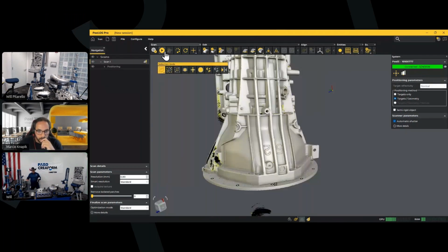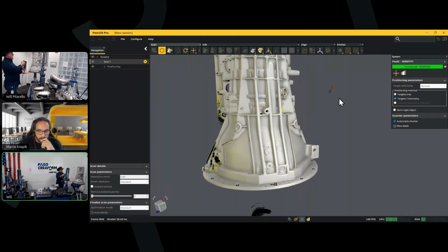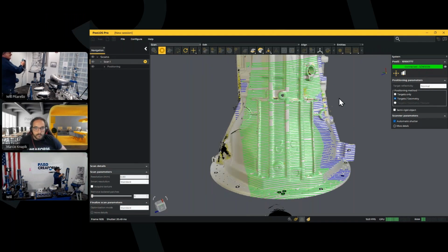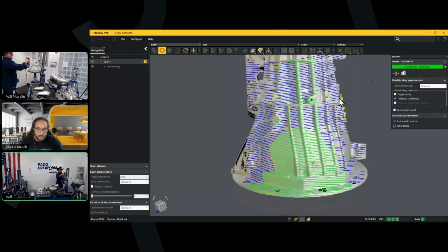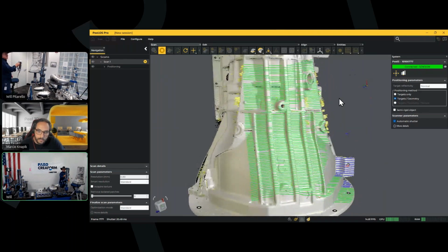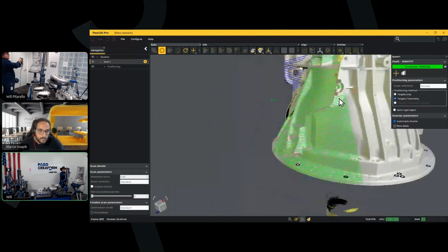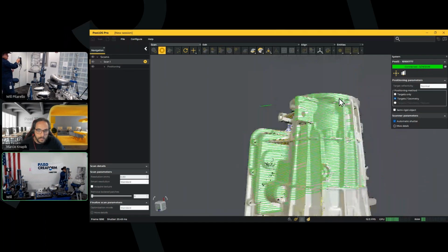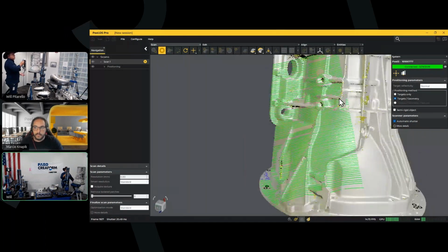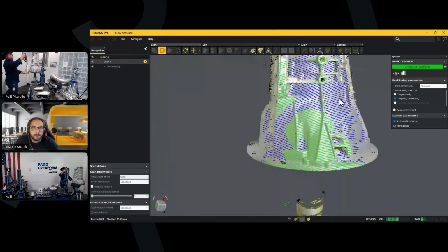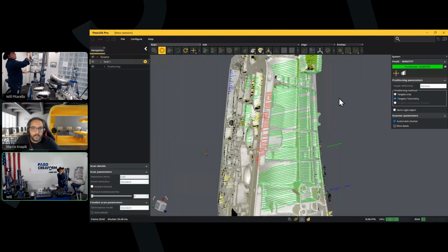All I have to do is press the scan button, go in, and look around where I need to. I'm going to give it a little bit of time for the scanner to get the proper alignment because it sees that number, 25 or 52. I think it's upside down. But now I can go back and cover the areas that were missing before. Again, it's using the geometry of the part to understand the alignment to the part where I left off. I can actually piggyback or pick back up where I left off. Great question though.